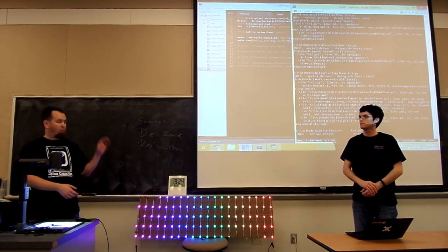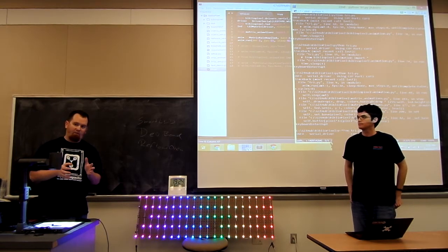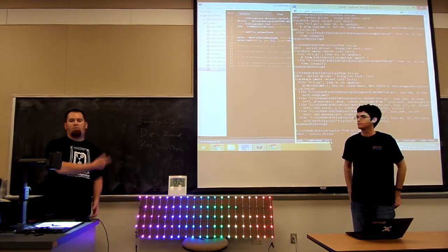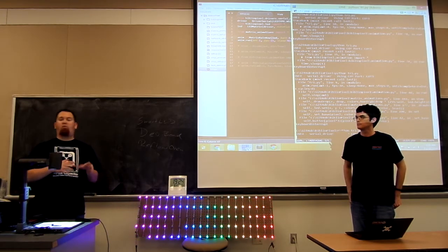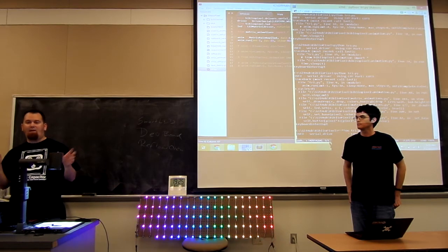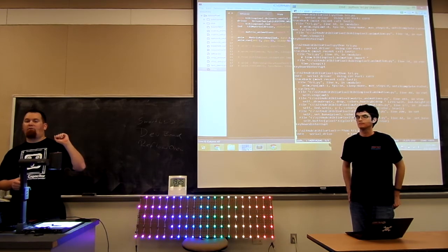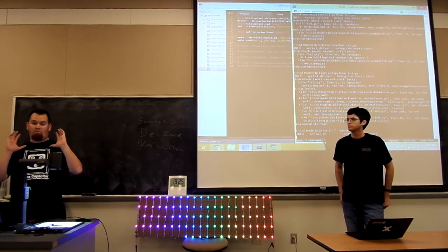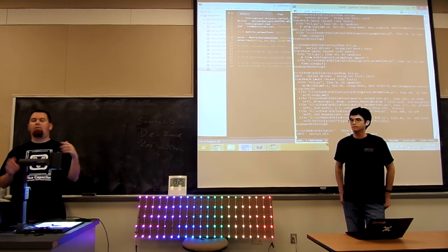different protocols. So with the WS2801s, you shift all the data in, pause for 50 microseconds, and then it knows, okay, latch, send them off. With the LPD8806, you can send them in willy-nilly as much as you want, and the reason they're 7-bit is because the 8th bit is reserved as a latch bit. So when you send in a byte that has the 8th bit set,